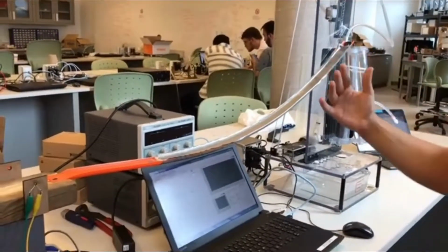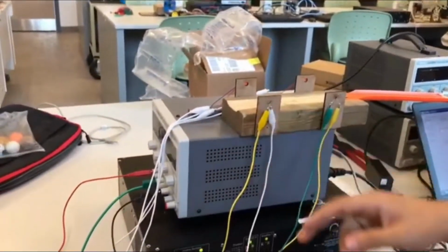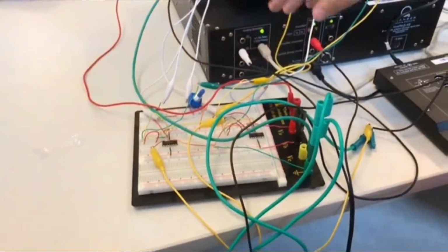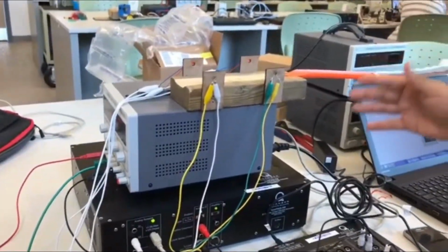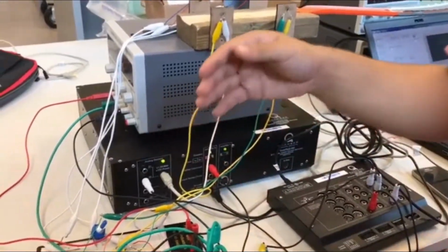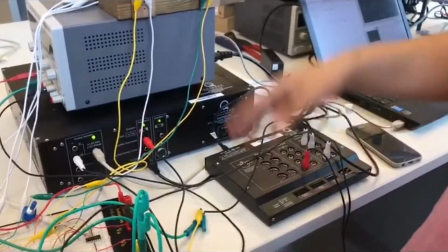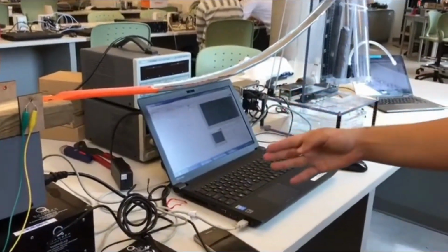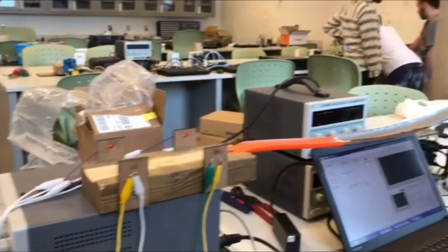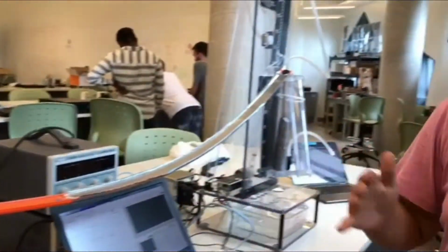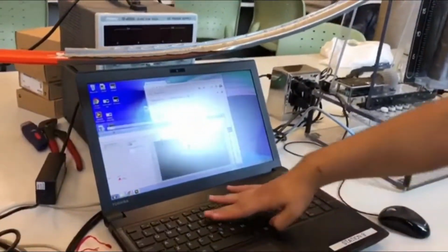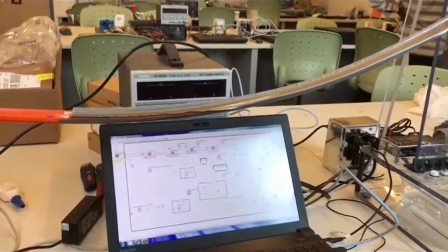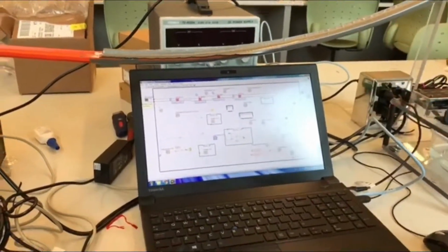With this signal, you'll be able to do different calculations. So the way this whole project works is that we have a power supply that powers the DAC, which has the circuit that controls the intensity of the lights of the lasers due to the room's light intensity. This circuit is connected to the DAC, which digitizes the analog signals coming from the diodes and the transducer, and sends them to LabVIEW. The energy difference between those two is basically the frictional energy, and using equations in LabVIEW, we can calculate the coefficient of friction of different objects and different materials.